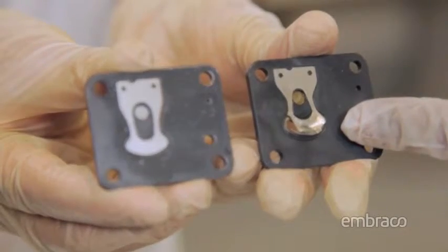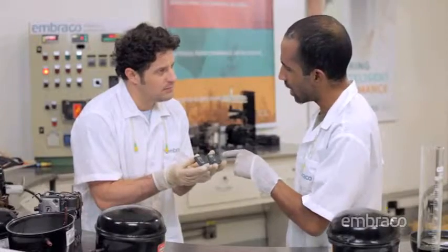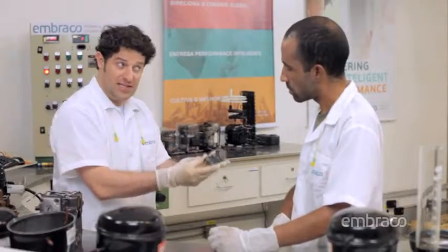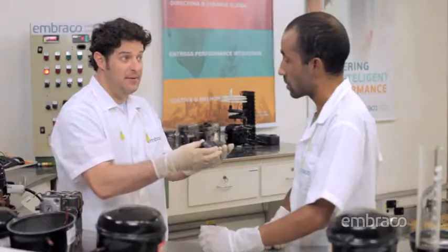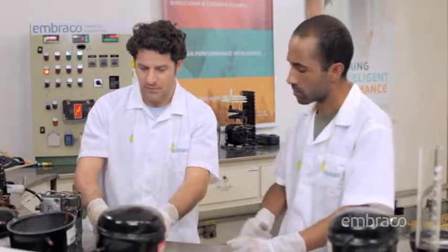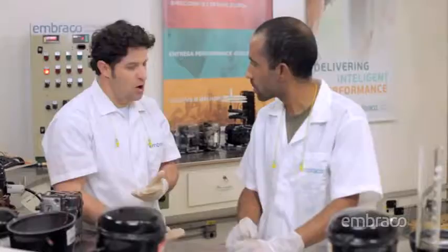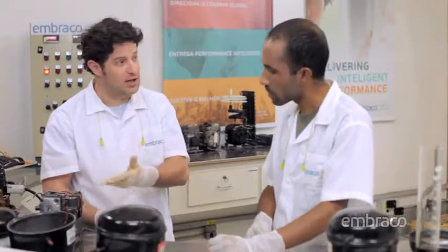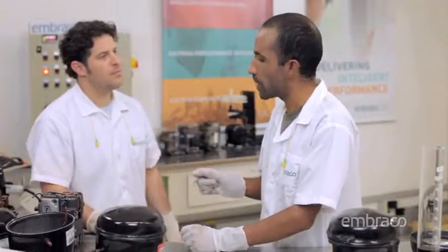In this damaged valve plate, is it related to excess gas charge? That's it! This warping or breakage may be related to excess gas charge, and in some more severe cases, the valve can break. But it might also be the incorrect compressor used. For example, a low back pressure compressor, LBP, being used in the system for medium or high back pressure, MHBP. Oh, for this reason, it's important to always use the suitable compressor for each system.